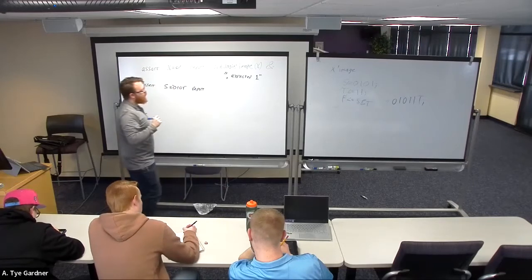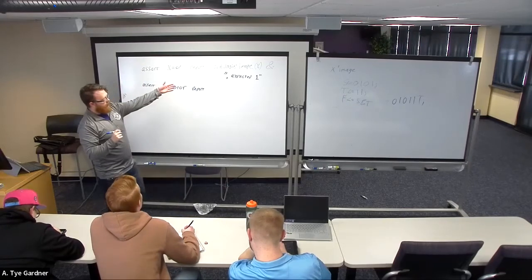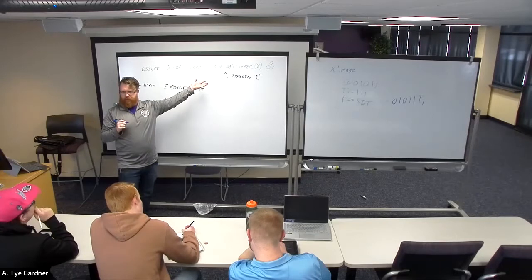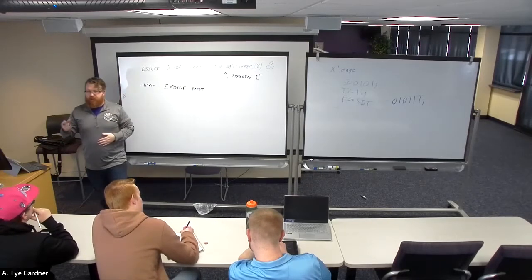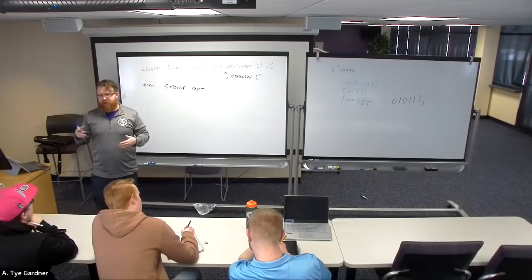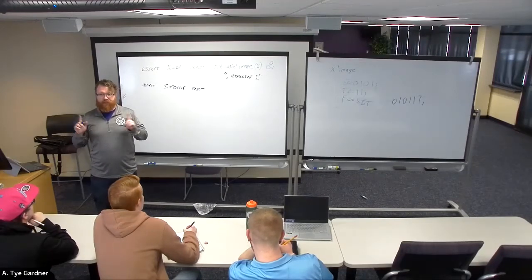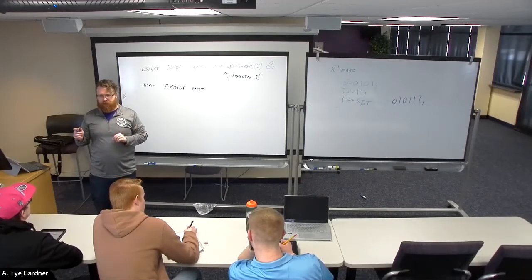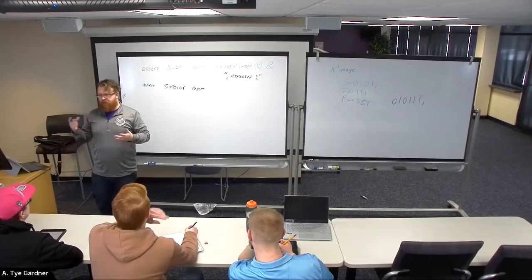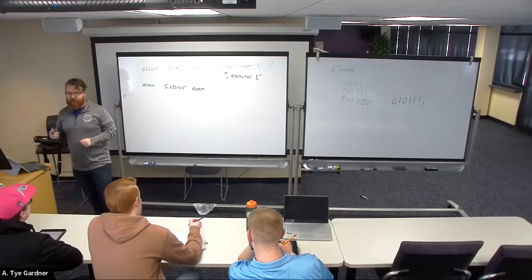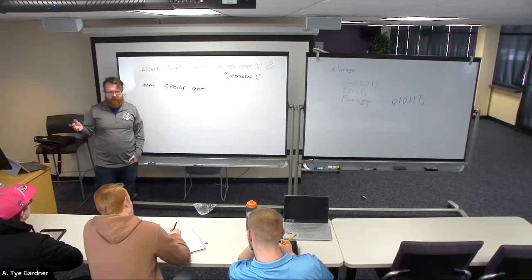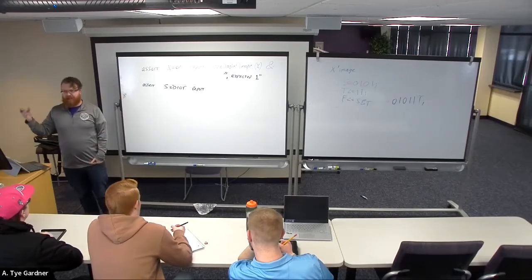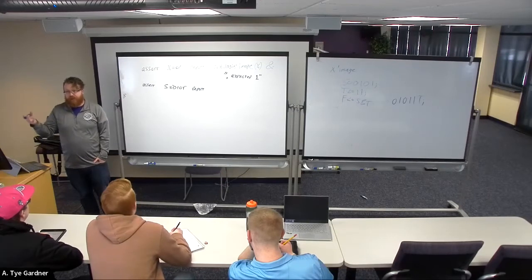well, I'd like to use this image property because it's already there for me, but it doesn't work on standard logic vectors. So now I'm going to introduce something else, which is type conversion, because it works on integers. It doesn't work on standard logic vectors. These are just different ways of storing the 1s and 0s. That's all the difference is between the integer and the standard logic vector. But it has a limited amount of capability of what it can do with the different types of data.